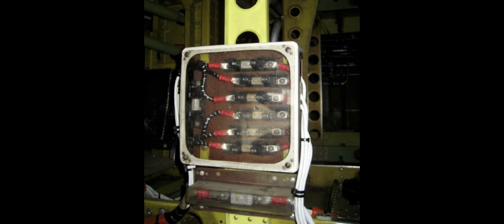Current limiters. The AC power system contains 6 AC current limiters mounted on a panel in the attic at station 154.5. The current limiters function like slow blow fuses to prevent excessive overloading of the AC generators during transfer conditions. When one generator fails, the primary AC bus loads from the failed generator are supplied AC power through the three limiters in the path from the remaining generator. The current limiters in each circuit permit loss of one or more of the three phases, while the remaining phase or phases remain online.